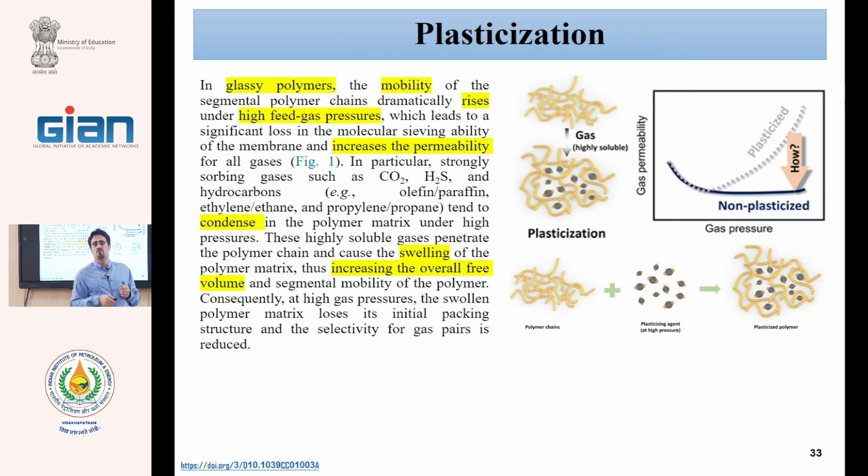And therefore, after a certain time, the flux increases and the selectivity reduces. After this time, 2 months, 3 months, 1 year, we say that the membrane has plasticized and changed its properties. The membrane will be brittle. The membrane was relatively flexible, but after 1 year it is very brittle and the properties are changed.